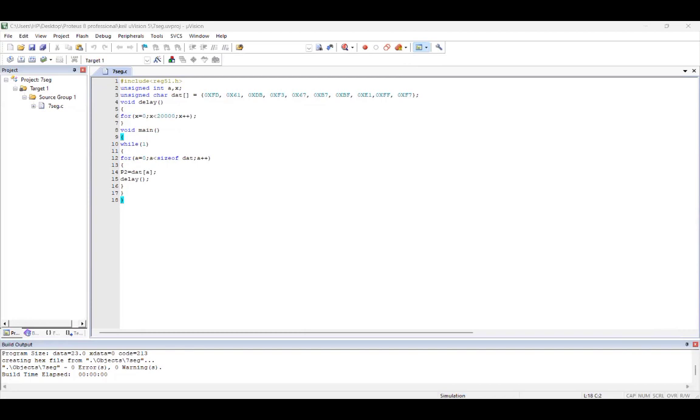You will go to this components option, which is marked P here. Then you'll search for AT89C51. See the first one, MCS 8051, which is the same. This one is here. You will click OK and you will get this one.